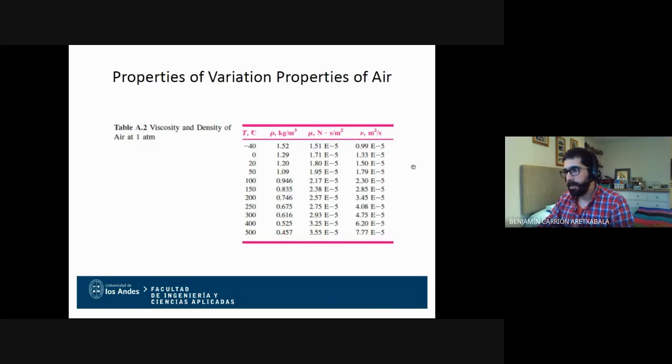And these are reference values for air. Again, you don't need to remember this by heart. It's interesting though that air is a lot lighter than water, and a lot less viscous, which is expectable. But it's actually tenfold more kinematically viscous, because it weighs a lot less. So kinematic viscosity lets you compare the effect of viscosity and the effect of density.